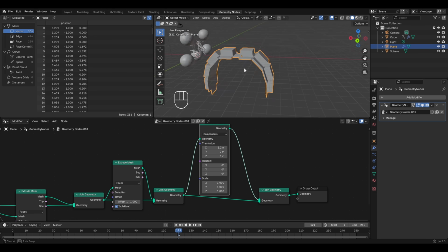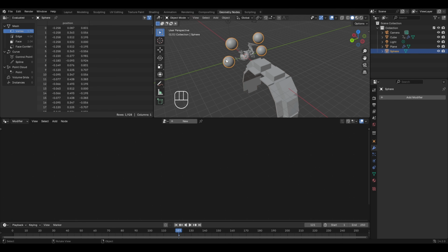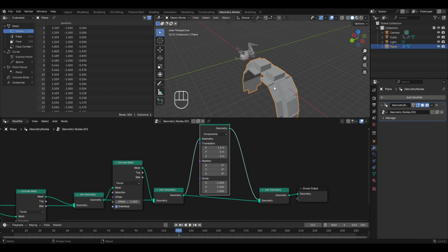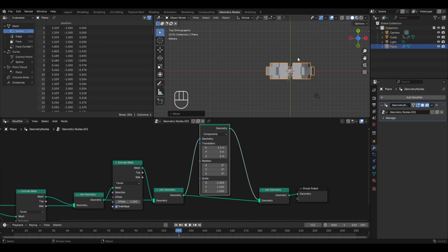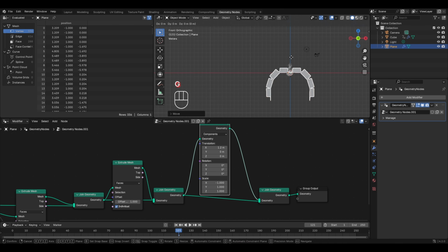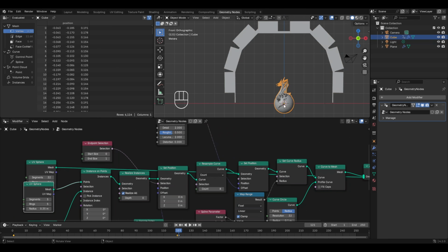Now we'll be placing this portal in place of these UV spheres surrounding the main UV sphere. So I'll select this, press X to delete, and to place this portal, press 7 to go to the top view. Let's move it in the x-axis and place it over here. Let's go to the front view also and move it upwards in the z-axis. Now to get the effect of these curved lines according to this portal, I'll select the UV sphere.